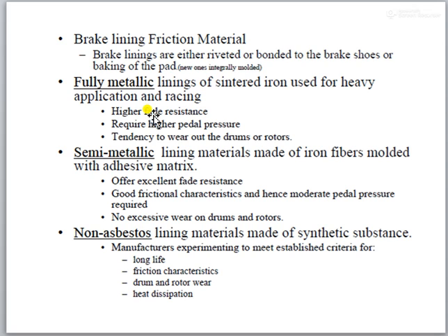So if we are using a metallic lining, that metallic liner will give you a less fading property, meaning it has high fading resistance. So its braking efficiency does not fade out. That is another thing, it requires high pedal pressure from the driver side. So to enhance the pedal pressure, we can assist the driver effort by some boosting force.